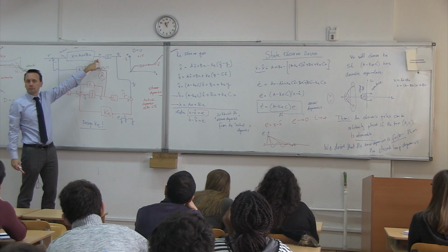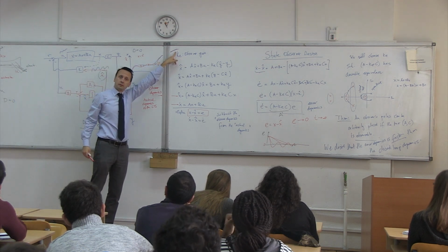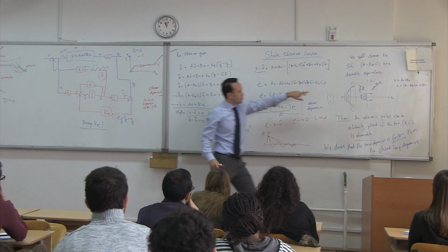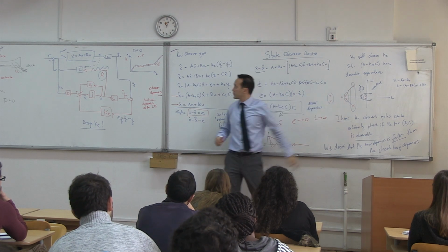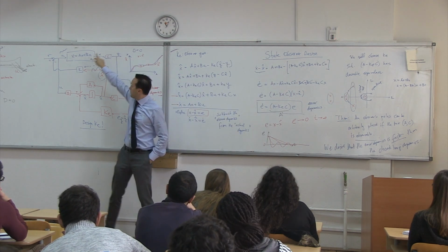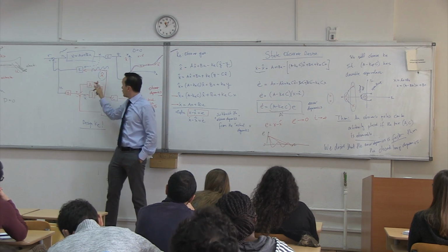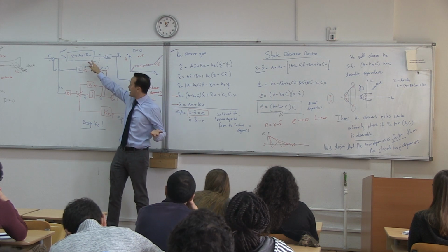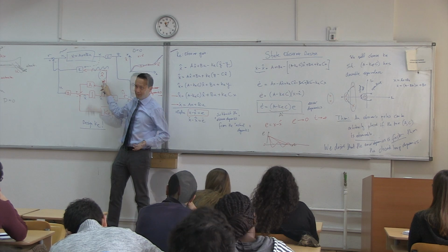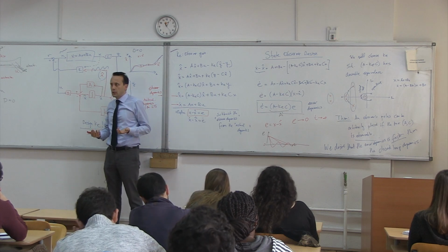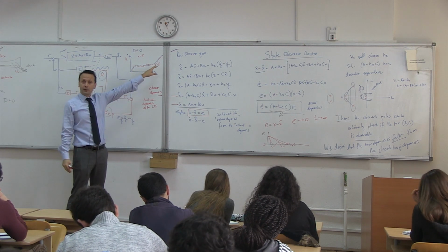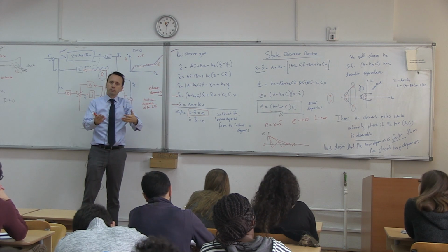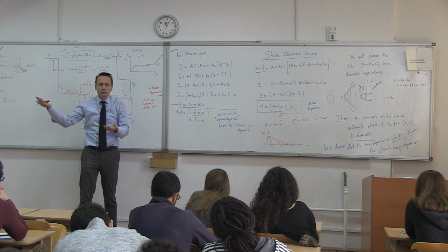Until when? Until these two are matched. Then you will generate the right U's and so on. So if you had an oscillating observer, it would in fact oscillate the system, because you would have an oscillating input over here, because you would think that you're oscillating. In fact, what you're oscillating is not real. I mean, the aircraft is not oscillating, you just think you're oscillating. You don't really want an oscillating observer. So what's going to happen? Well, you're first going to oscillate for a while, and then you will match this one, and after that you will converge to your steady state, whatever.